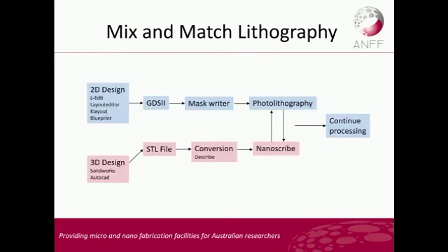There's not one software environment that allows you to do it. The only way to do it is to go through your normal lithography design process in order to do the photolithography part, and then to do 3D, you need to just sort of fudge the two and get the two to align together. So you just need to understand your design, understand the dimensions, and make sure that the two overlay each other.